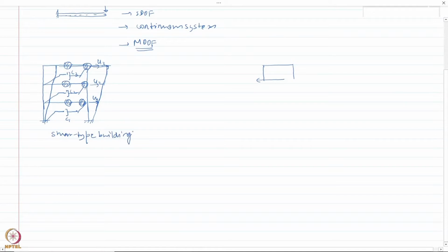So if there is a relative deformation between the floor and the roof of a story, then story shear is generated. One would be due to the elastic deformation of the columns that connect the floor and the roof of that story, and the second would be if we are considering damping. The first is the stiffness contribution to the story shear, which is written as kj, the story stiffness.